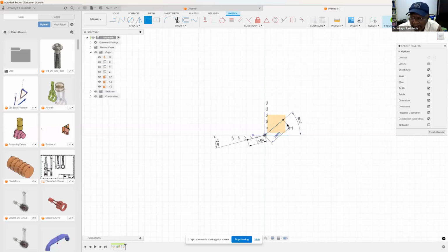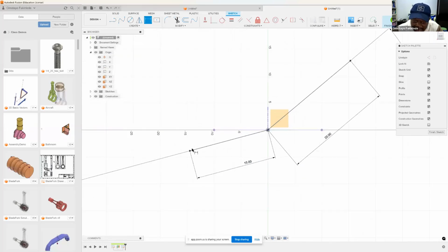Let us look at it. You can see that this line has a sharp turn here, and I don't want this sharp turn. Because I don't want that sharp turn, I can put in a fillet there. I can choose my fillet between this and this. I want a fillet of radius 40. So with that, this is radius 40.